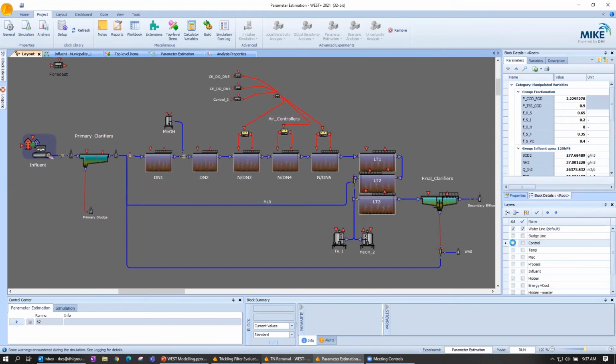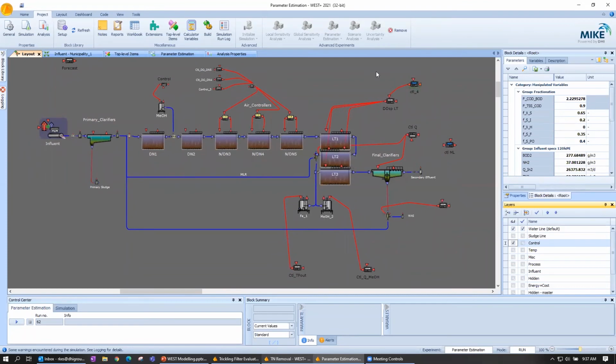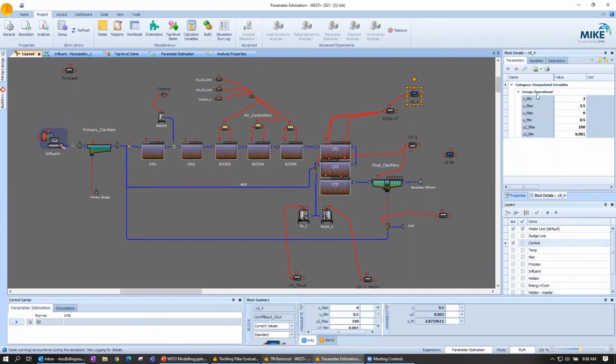And then if I unlock it now, we can see there's actually a lot more controllers. There's DO discussion going on between these 2 controllers for the DO setting for the aeration tanks, and of course mixed liquor control, RAS flow, and chemical controls. So to tune each of these, you can just start up the plant and start tweaking valves and parameters, but that's a lot of work. So what we can do is change them in a virtual space instead.